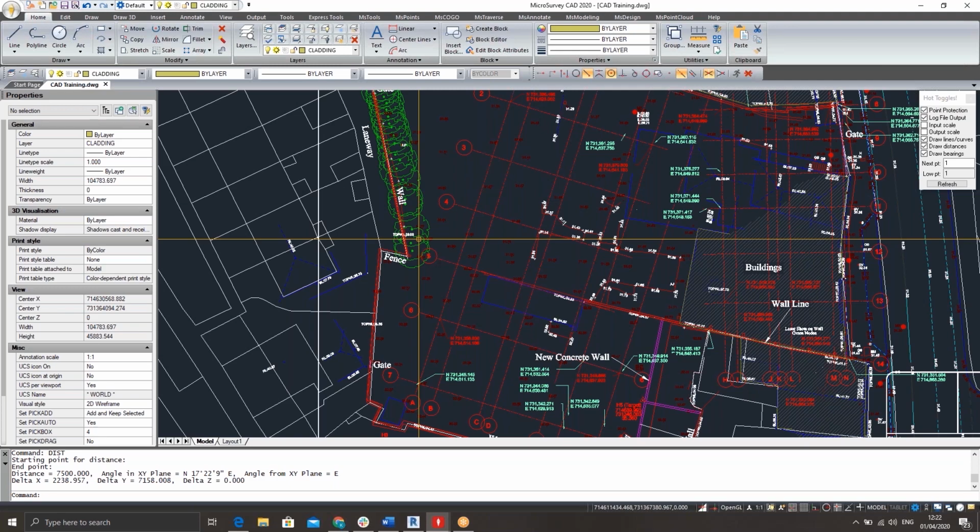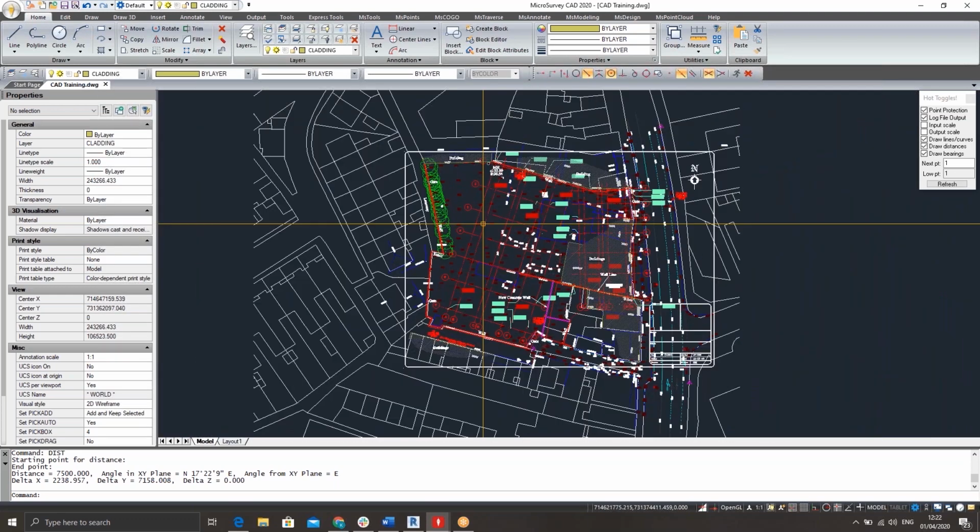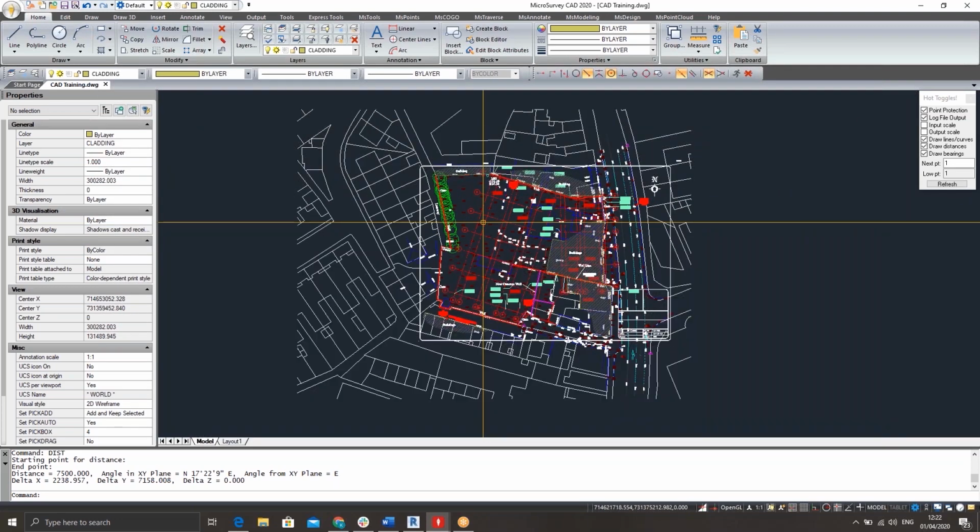So we need to understand our drawing before we import it into our field controller. It is not an issue with the drawing being millimeters or meters because in our import configurations within our field software we have the option to specify what unit the drawing is in. So it's a good first step. So what we can do then within the framework is we have an option: do we want to scale our drawing or do we not want to scale our drawing? So once we've identified, we can just make a note of it. We don't have to scale it. I'm going to scale it in this example for you guys just so I can show you how it is possible to do.